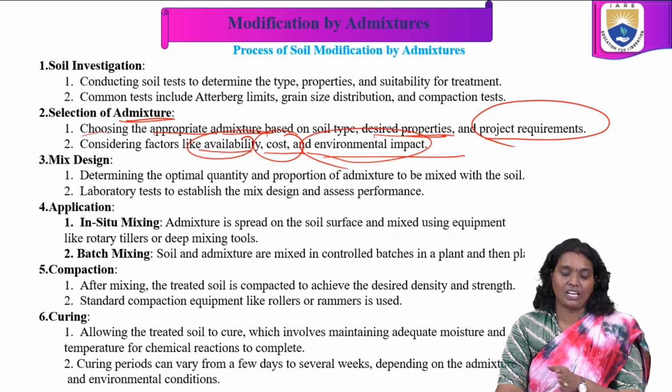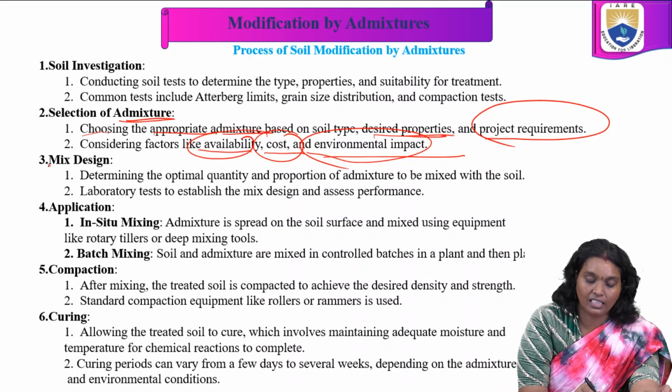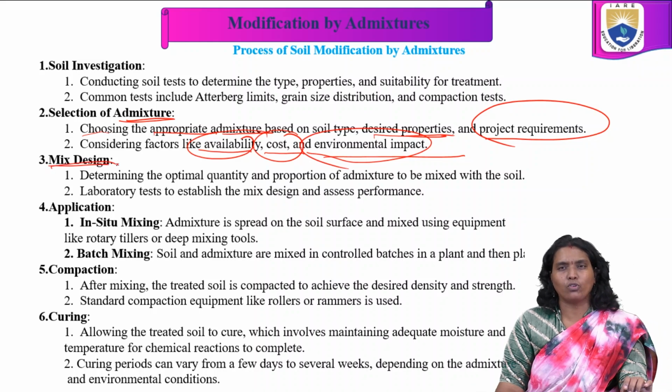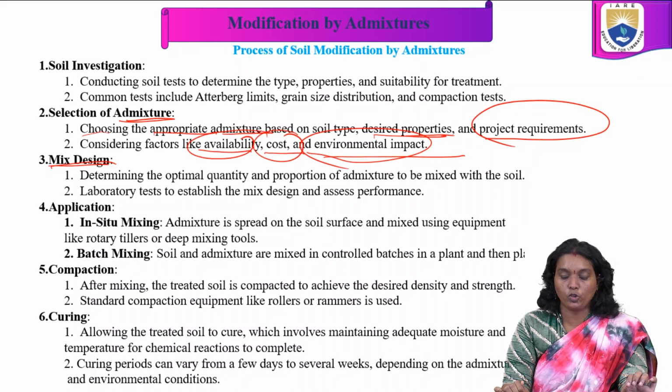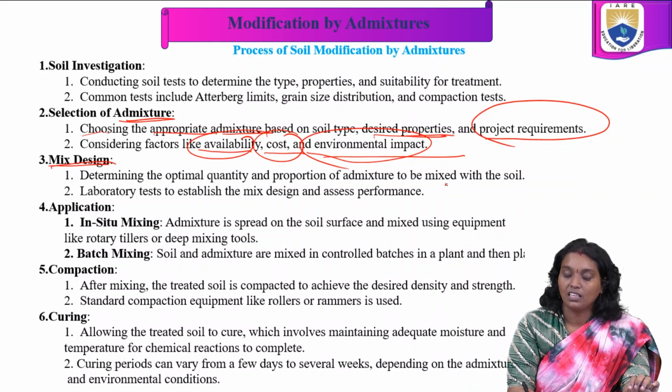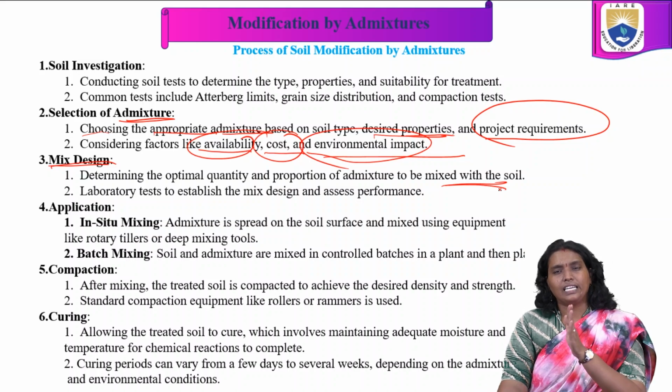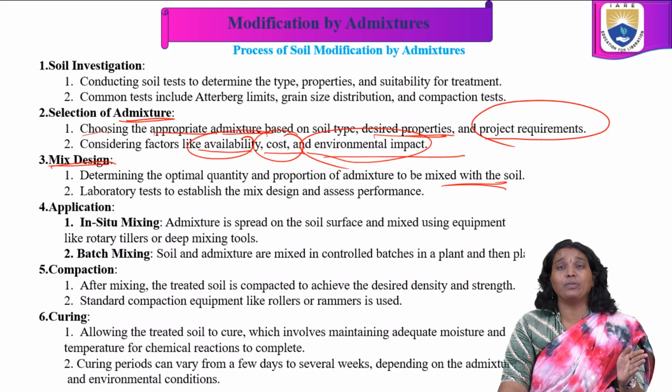After that we move on to the next step, the mix design. In the mix design, we determine the optimal quantity and proportion of the admixture to mix with the soil. It depends on which type of mix is required.